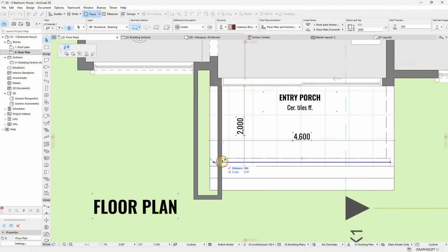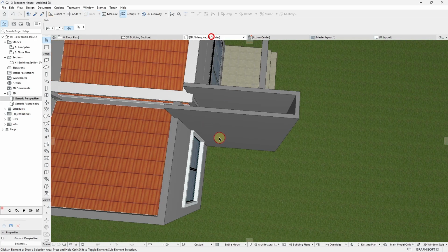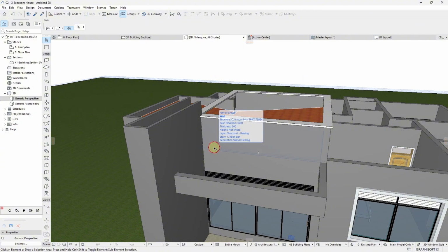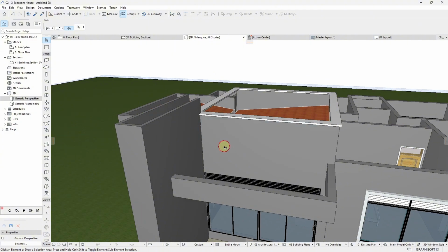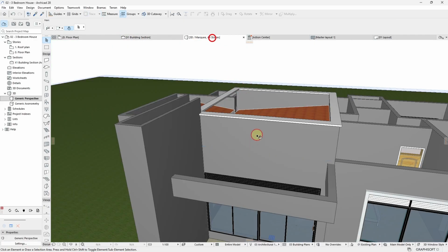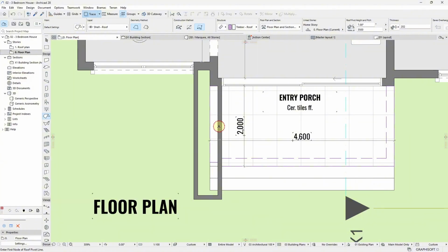And then also here at the balcony, let me just bring this out a little bit. Okay, here. At the balcony we also have a roof. This roof is going to be a low angle roof, sloping slightly. At the balcony it's all up to you. If you want to drain it towards the building, it's okay, or drain it towards outside. But I think draining it towards the building might be much better.